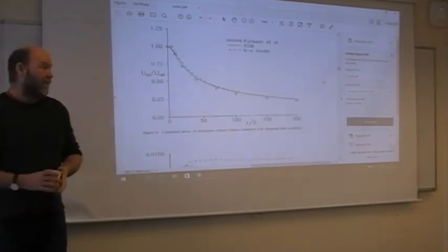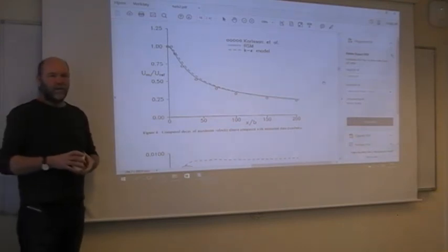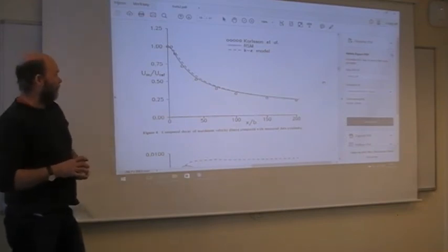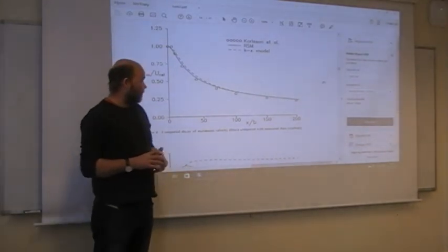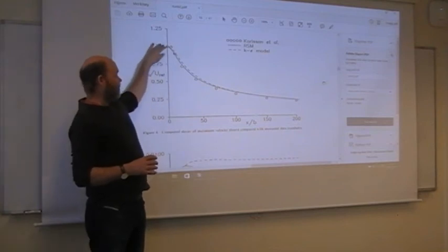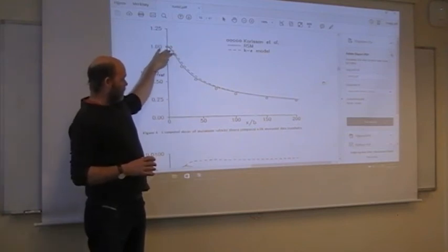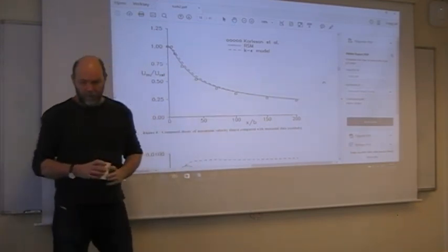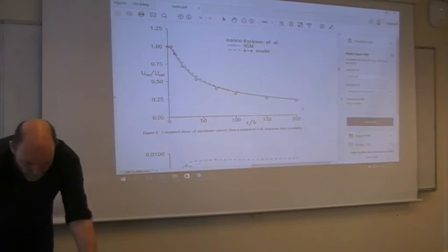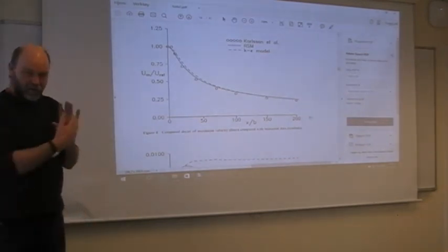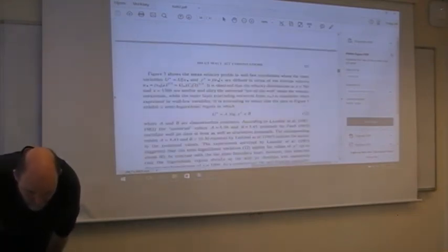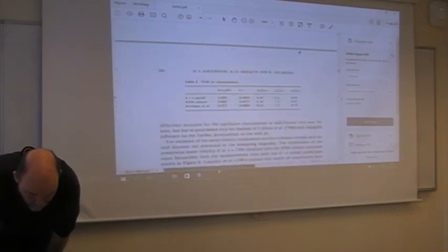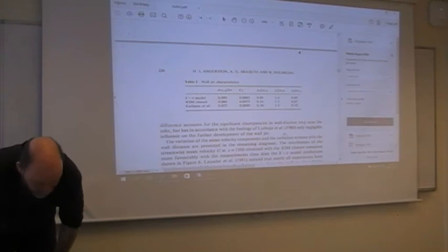The average velocity, well, that's not so tricky to get. So even with a laminar flow, you will get a fairly decent velocity profile. So here the maximum velocity in the jet, how it decays from the max at the inlet, so 1. So it smears down a little bit. But you have to go pretty far downstream before the jet is totally killed.